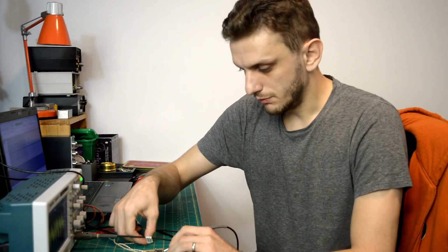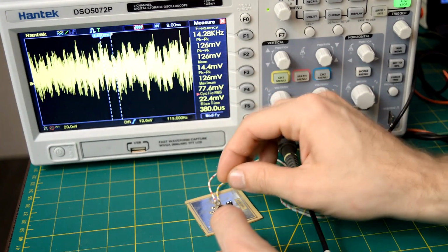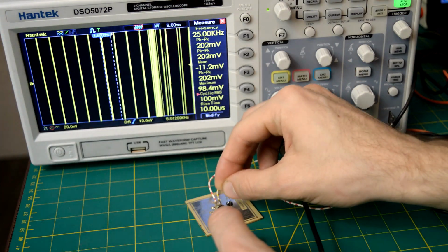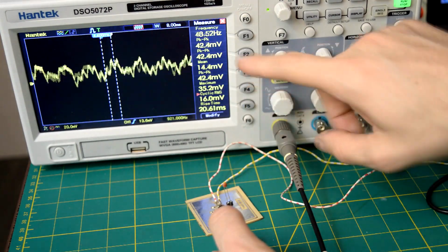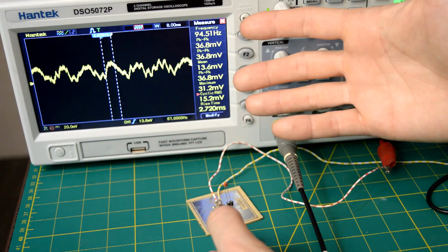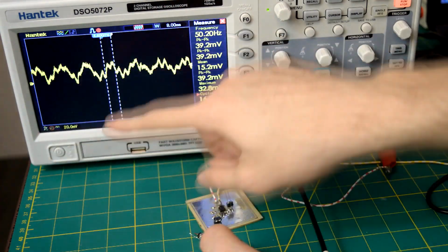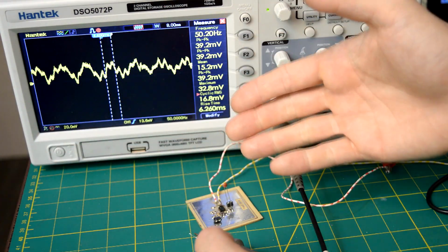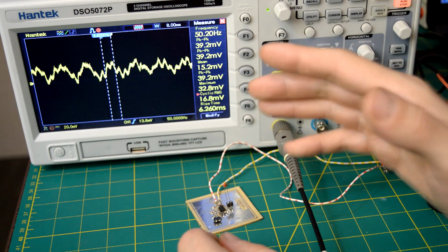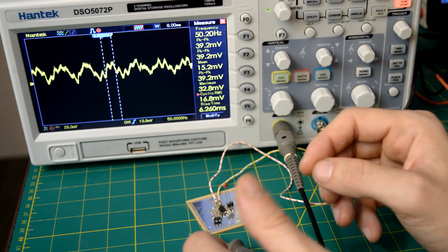Now, if we take the capacitor and add it into the circuit, so I prepared this little connector here to ease this connection, we see that our waveform now looks completely different. So we didn't just reduce our peak to peak noise, but we also changed the shape of the waveform. So we see that we no longer have a high frequency content, so there's no more spikes going through it. We just see this slowly changing waveform. So the spectral content has definitely been reduced.